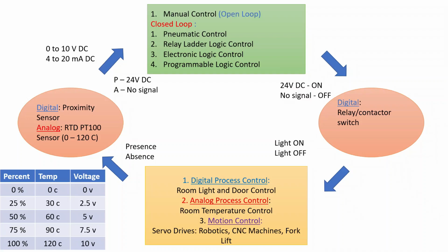So, if we have a set point of 20 degrees C, and a process variable of 30 degrees C which is sensed by the RTD sensor, that means the sensor is sending the signal of 2.5 volts DC to the controller as given in the table. Then the calculated error is minus 10 degrees C, so to overcome this error the controller should turn on the cooling element. The cooling element would be a throttling flow control valve to control the cooling fluid.